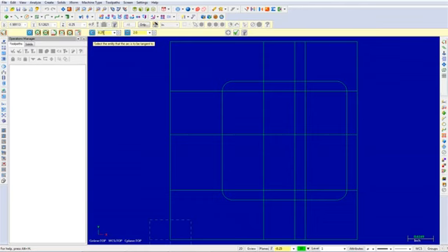Select the horizontal line as shown. Now specify the tangent point. Select the intersection. Now pick the arc that you would like to keep. Select the following arc. Once finished, choose the Apply button to stay within the command.